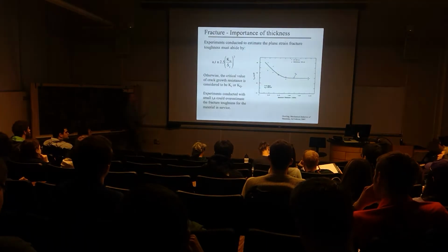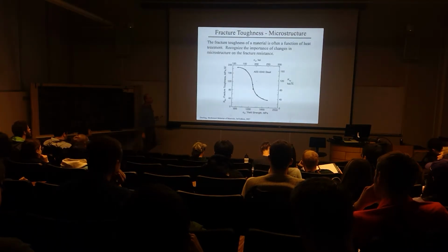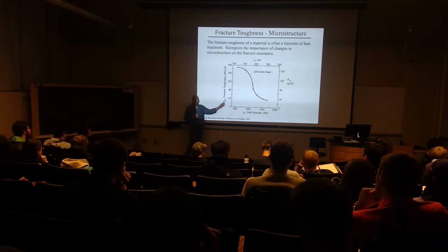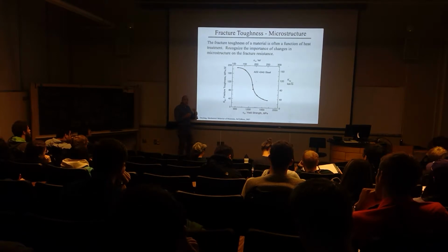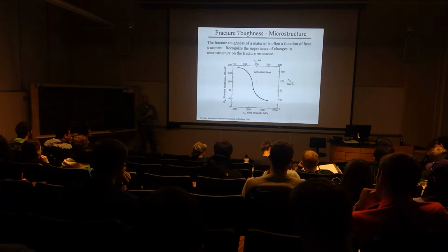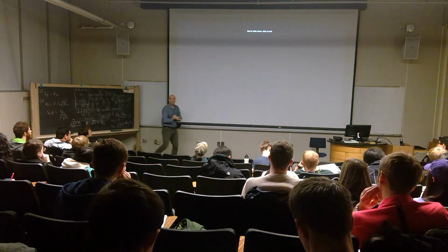So yielding can be lost, or a yielding phenomenon in terms of material can be lost. So be careful. Be aware of heat treatments that were used, but not necessarily done appropriately, or they were used by someone who thought that it was smart to increase the yield strength more and temper back a little less than really was probably appropriate for resisting fracture. Okay?